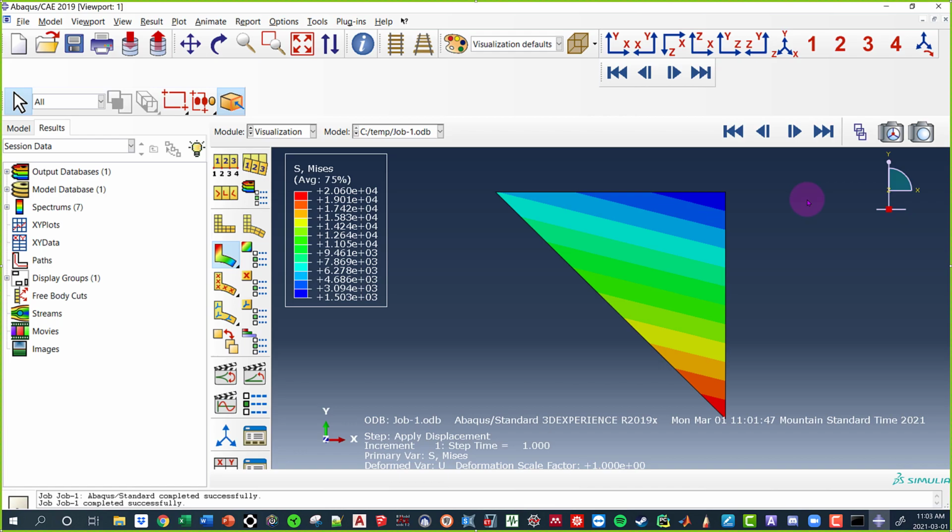What about K11? It'd just be the horizontal force at node 1. Yeah, I didn't think about it, but I shouldn't have put it as a 1, 1 element because then I can't really measure it. And I guess I can't anyways because of the probe value, but that's all you guys do. Apply your unit displacement, probe the 4 nodes for your 8 values, move on to the next one.